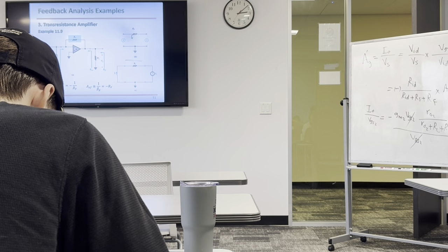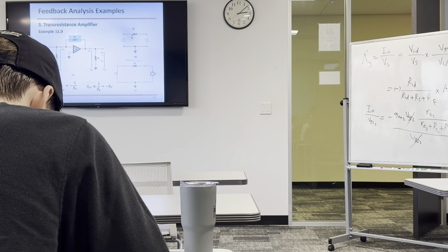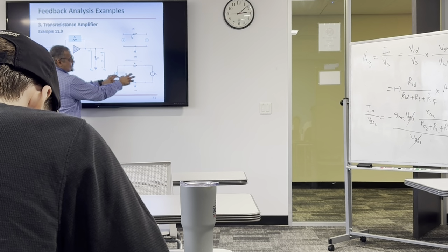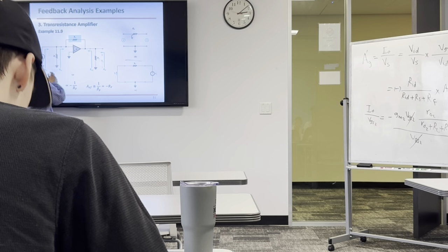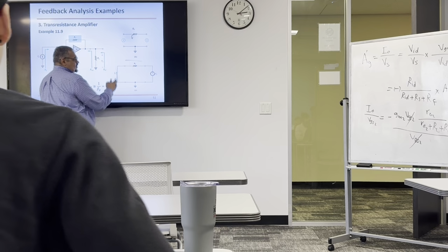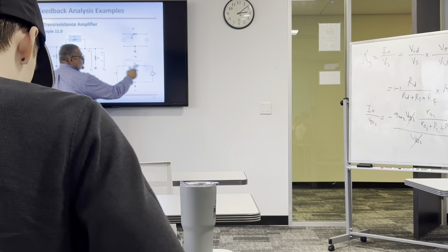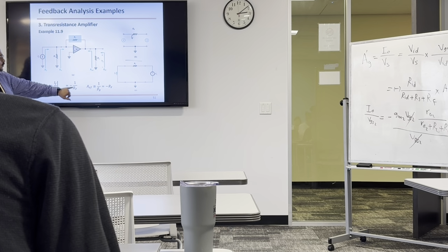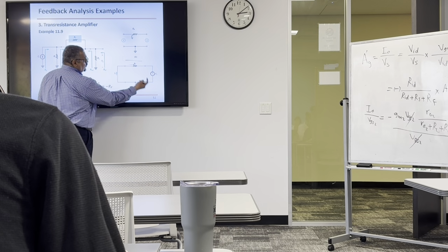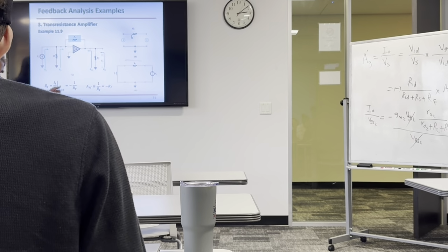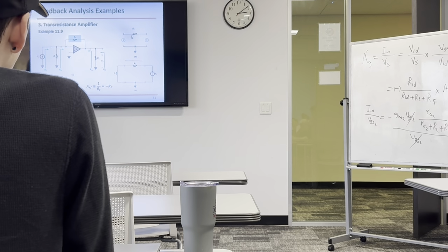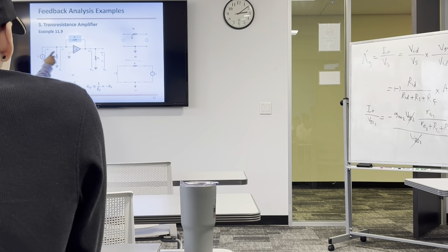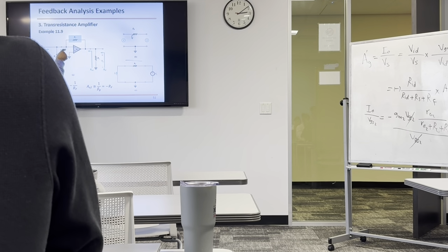Okay. So this one is the transresistance, with this being the feedback. And if you take it out, it's going to be like this. And since the output is voltage, the feedback is current, then you short circuit this, right? Because this was current. And then you can find the relationship between IF over Vout. And if this is the case, this is going to be minus 1 over it, because the current is going this way while the voltage is measured this way. So there is a negative sign. Now we isolated RF, then we have to add it twice. Tell me how to add it twice. First of all, this is what? Is it voltage mixing or current mixing?